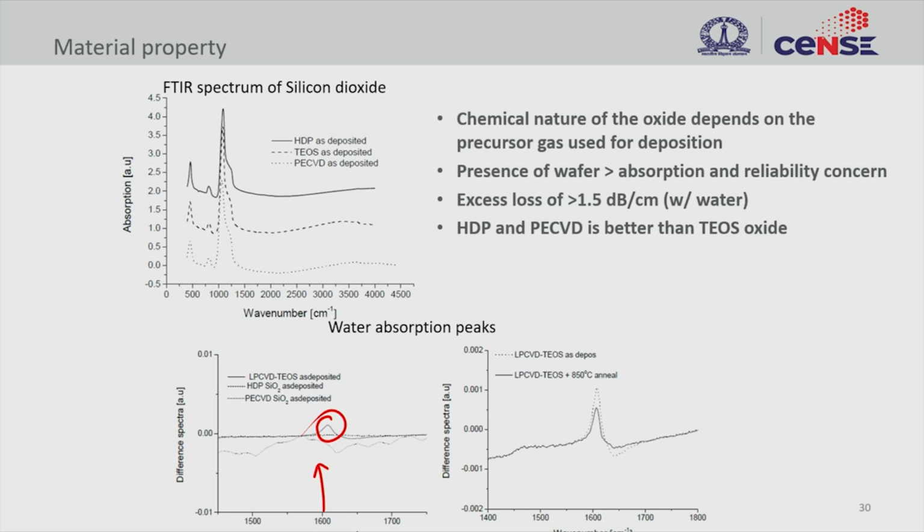So even when you anneal it, right, you have the as deposited film here, and then even when you anneal it at high temperature, there is still some water vapor present there. So post anneal, when you are going to cool it down, water, or rather the humidity, can diffuse in, and then it will occupy the space that is available inside this oxide material deposited with LPCVD.